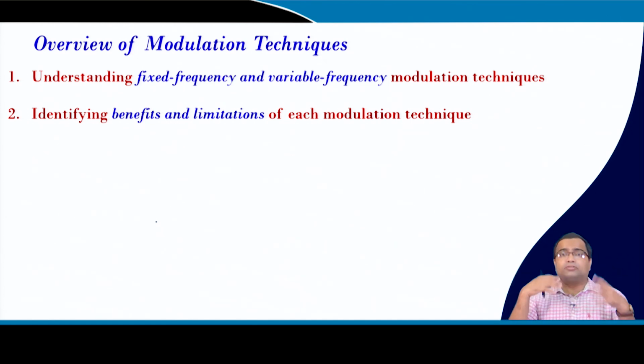Then we have also understood that variable frequency control, such as constant on time and constant off time, even for voltage mode, can be much faster than traditional voltage mode control. Also in current mode control, the variable frequency current loop actually makes sure the current loop is inherently stable for the entire operating range.